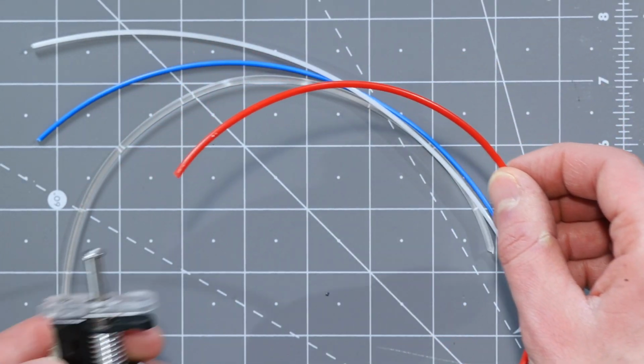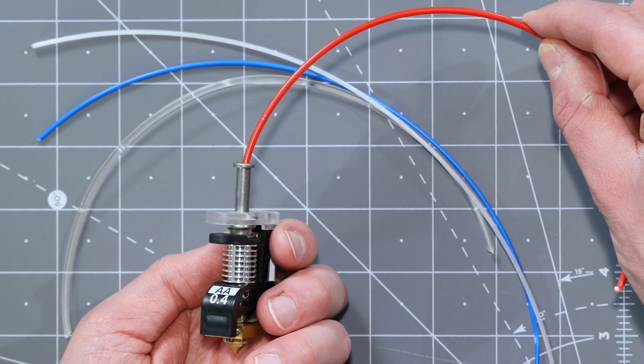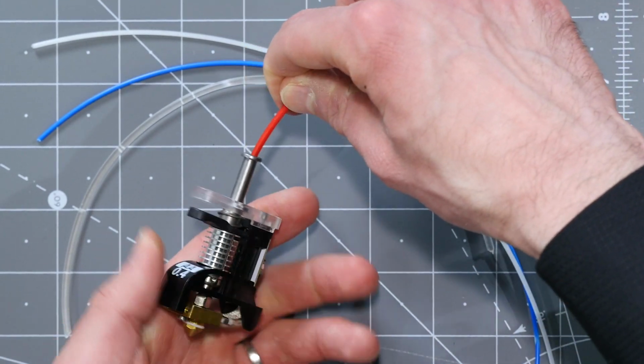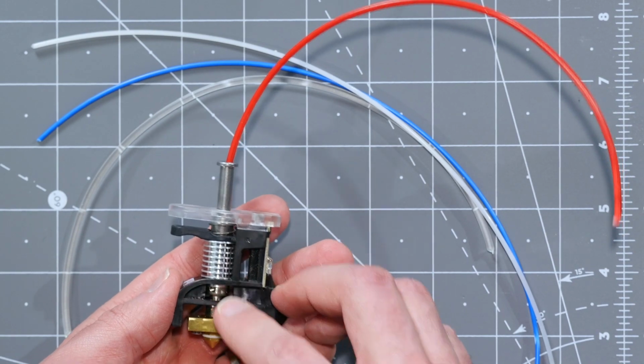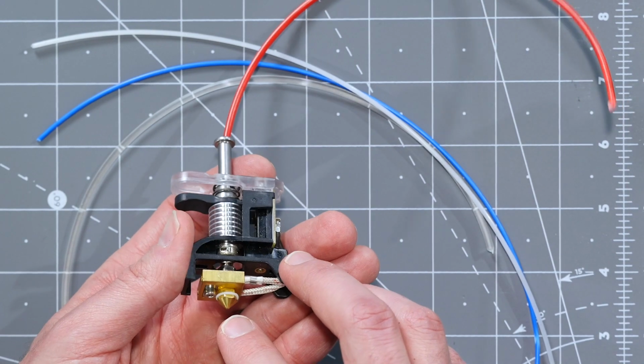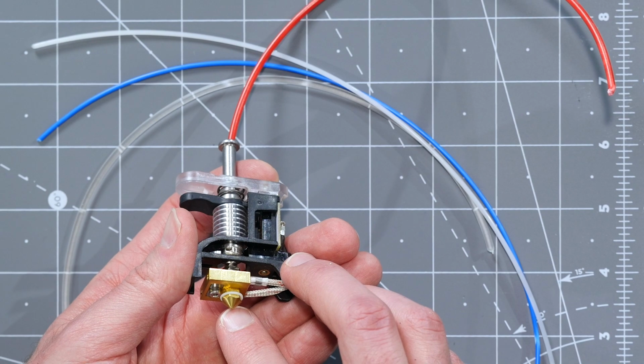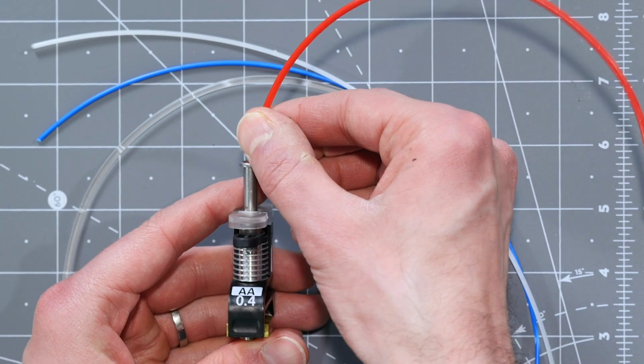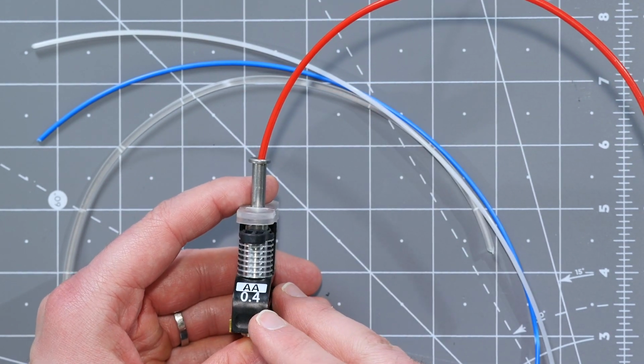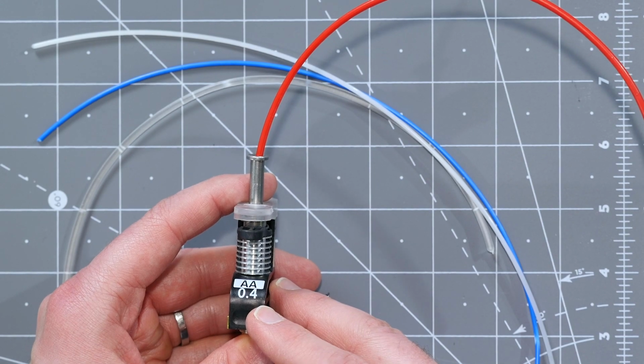And this filament would be conveyed into this print head from the desktop 3D printer beside me through the top, where it's then heated to its melting temperature before it passes through the nozzle. And at the bottom of the nozzle it exits and it's laid into the part layer by layer. According to the label here, the nozzle diameter of this print head is 0.4 millimeters or 400 microns.